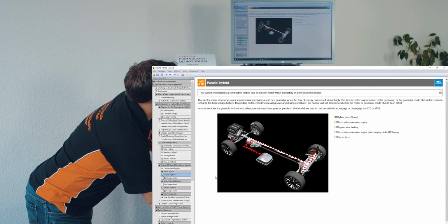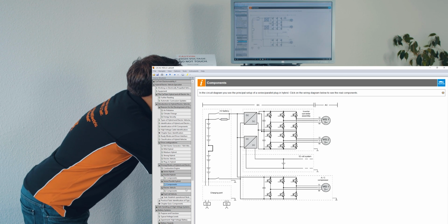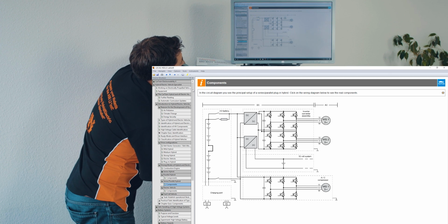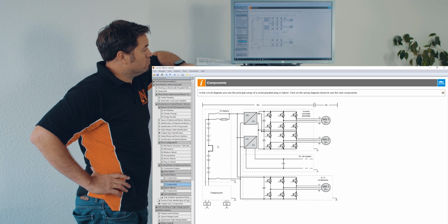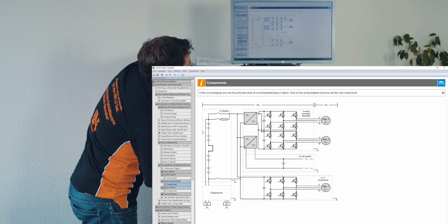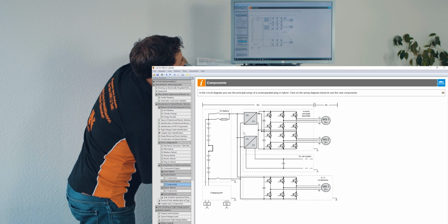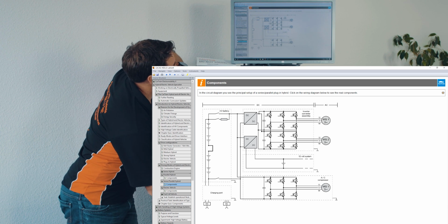So all of the different types of hybrids are shown here. We've also got the schematic, basically just showing the very basic outlay of a hybrid vehicle. We've got the high voltage battery right here. This section here is all considered DC, so to say. We've got the inverter right here. This is where the DC voltage comes in and is then converted to AC voltage.